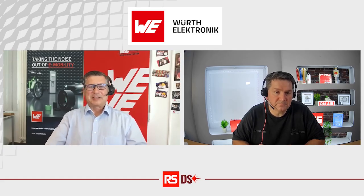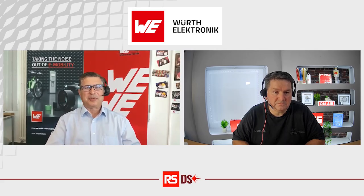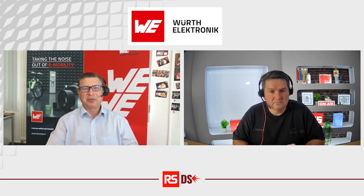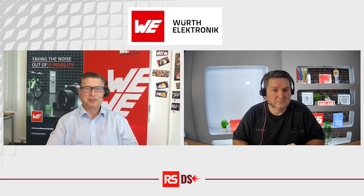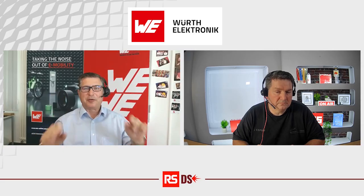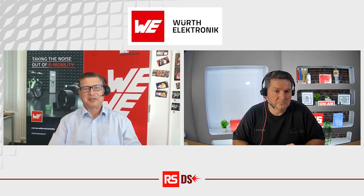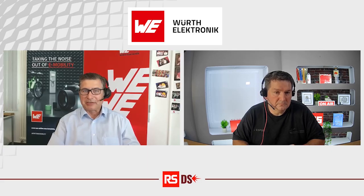Well, after the resistor, I think the most used component in every electronic design is a capacitor. And then comes the inductor and the rest of the components. A capacitor has a very simple role: to store some energy for a very short time. It can charge fast, it can discharge fast. It can also be used, instead of a transformer, as a small galvanic decoupling in a signal line or something like that. But actually, this is a simple passive component which has also some hidden tricks.